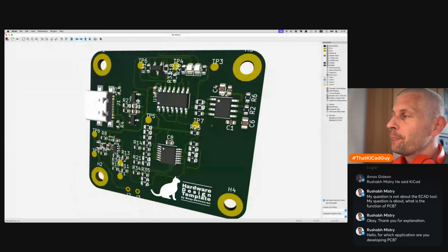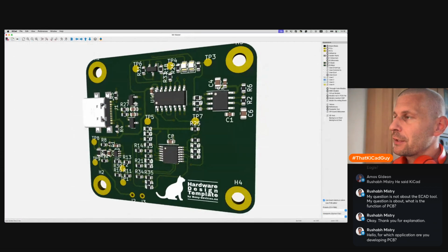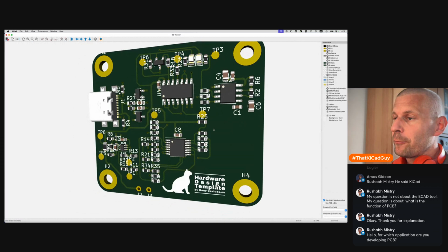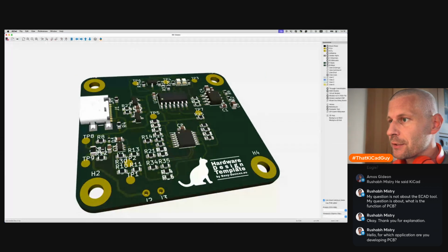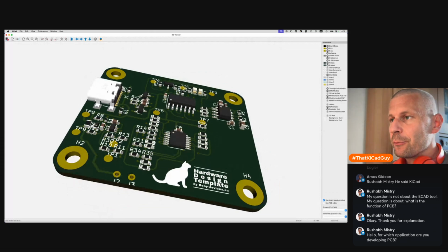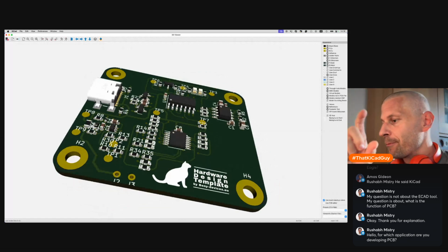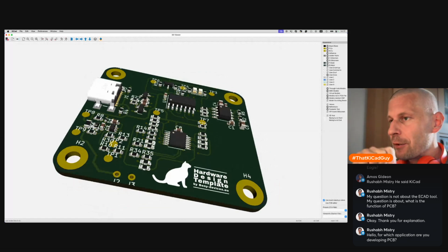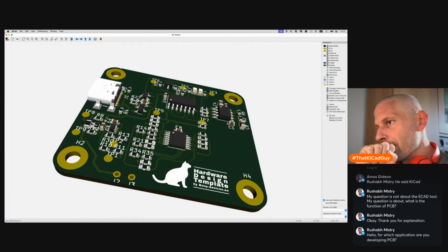The components are near the edge of the board, so the access to them will be comfortable, as well as these two output pads. I placed them close to the board edge because I use the hooks on the cable.